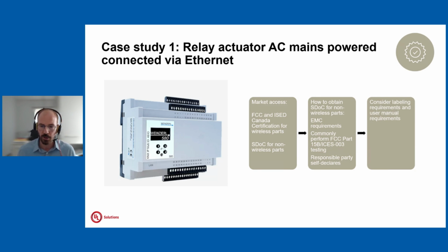One of the things you need to be familiar with is that in Europe, when we're talking about EMC and the EMC directive, the EMC concept has both emissions and immunity. So we need to demonstrate compliance that the emissions of the device, conducted and radiated, are within certain limits, and also that the device can withstand certain levels of immunity, from ESD to surge, depending on the port and the product category.